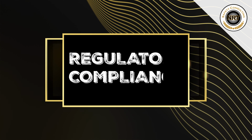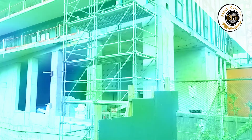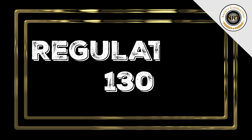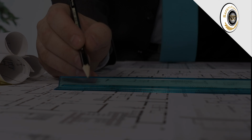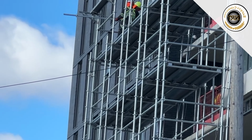Regulatory compliance. Following Regulation 126, scaffolds must be designed to support at least 4 times the maximum load expected. Under Regulation 130, it is required that scaffolds over 15 meters in height must be designed by a professional engineer. This ensures stability and safety of the structure.